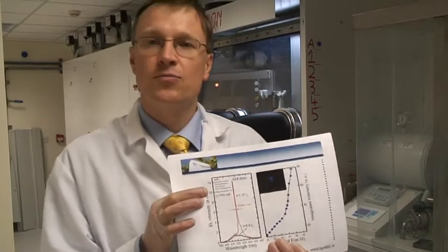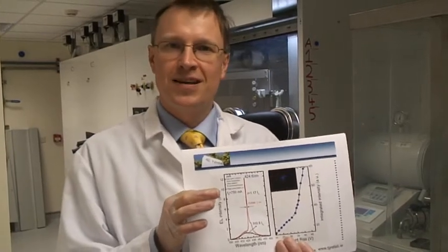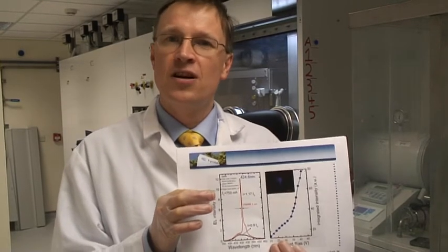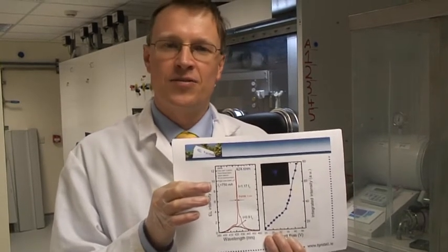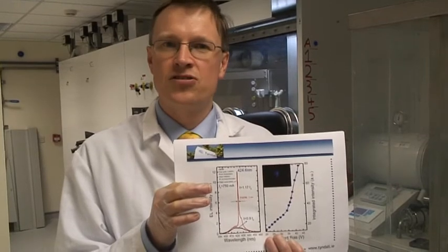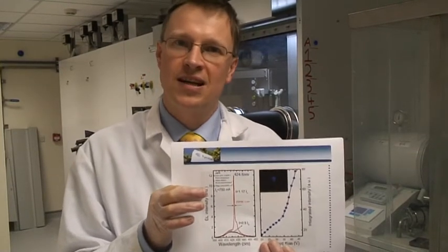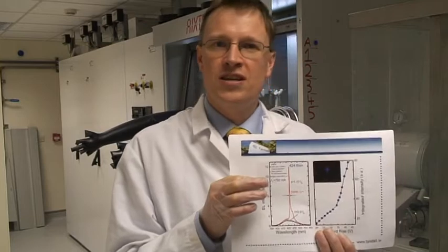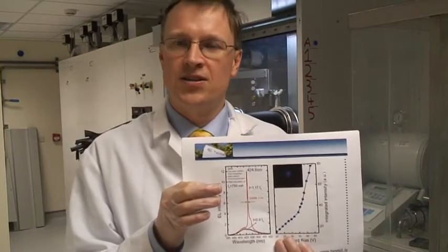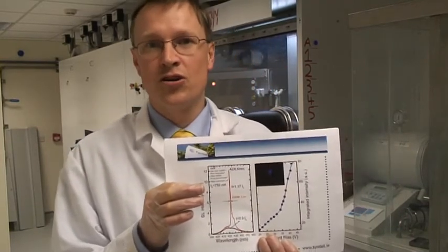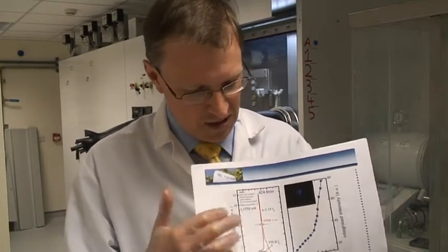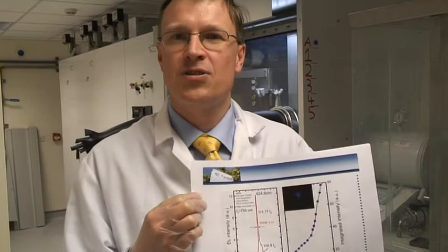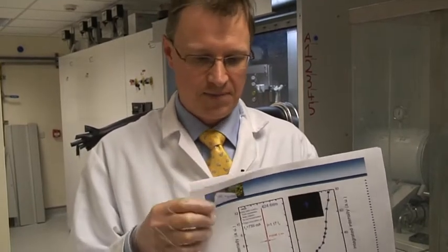This shows an image of some of the other applications. Firstly, we can make a laser. Commonly, gallium nitride lasers are most well known for being used as the enabling technology for a Blu-ray disc drive. In a Blu-ray disc drive, you have a 405 nanometer laser, which provides the read head for the optical pits on the disc that provide the movie or computer information. This shows a laser that I made in a previous place, which shows strong laser emission around 420 nanometers.